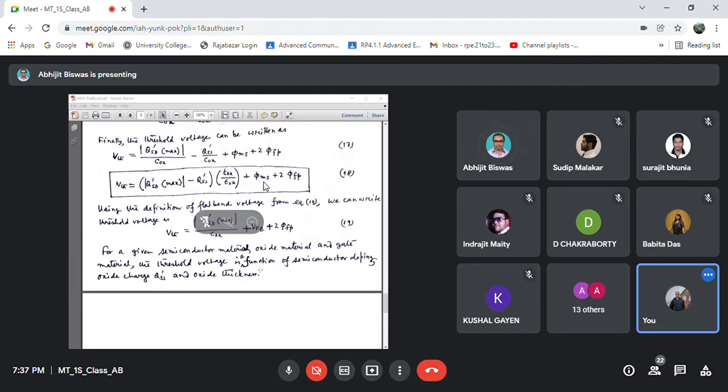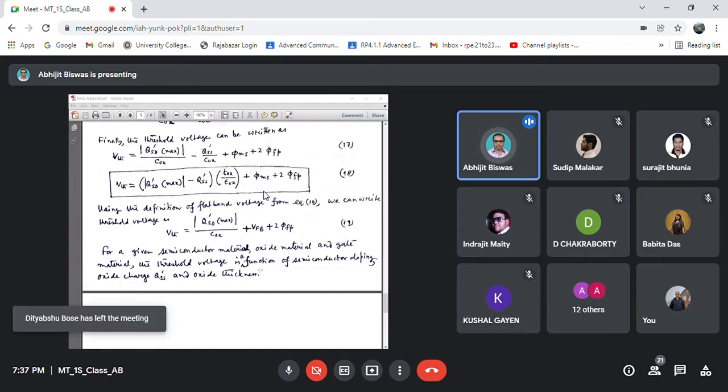Yes. So it is a clever technique to vary the metal semiconductor work function, because you can choose different metals. Metals are available with varying work functions. And some composite materials are there where you can vary the work function, that is TaN, this combination.